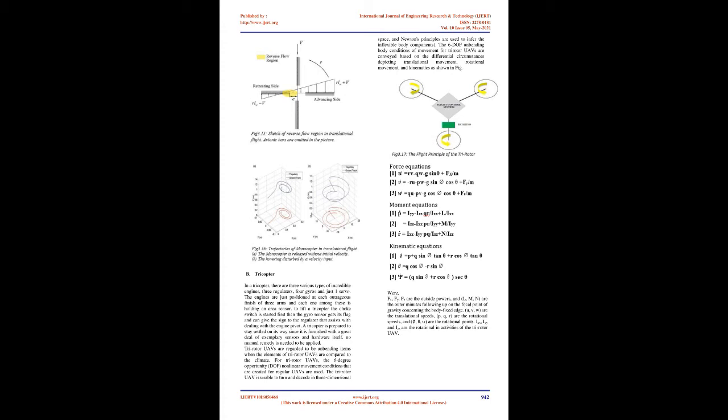Mathematical model. Blade element aerodynamics. The above figure shows the inflow sketch at a representative blade element on the single wing. When the vehicle is rotating at a rate of Ω = [p, q, r]ᵀ, the local translational velocity of the blade element can be described as, where l_b is the blade element's radius vector and l_b = [l_b, 0, 0] in the body fixed frame, V_CM is the vehicle's center of mass translational velocity, and V_CM = [u, v, w].